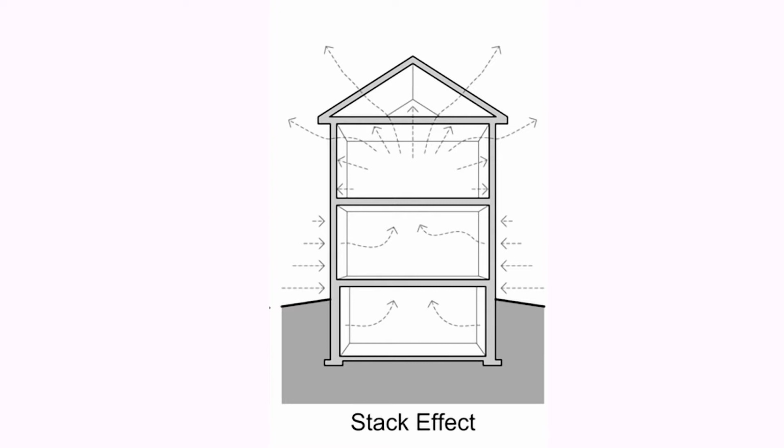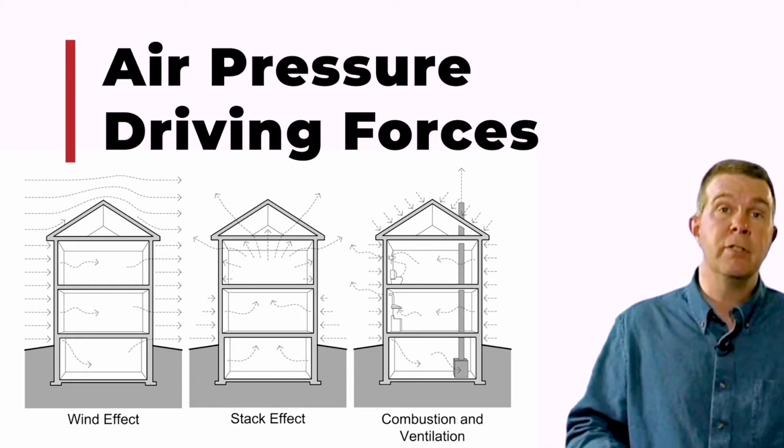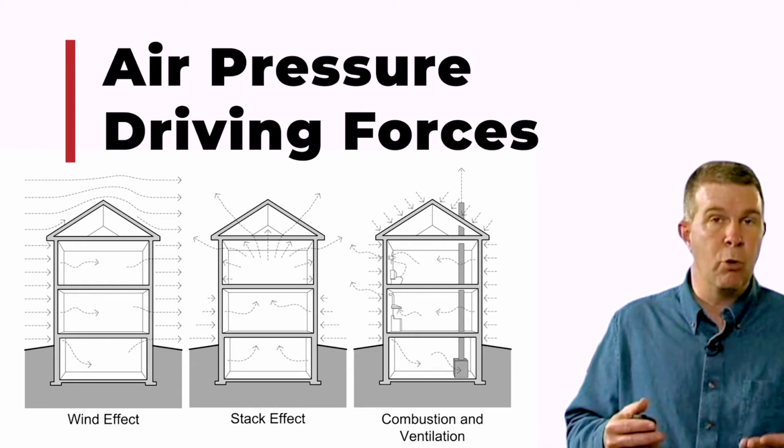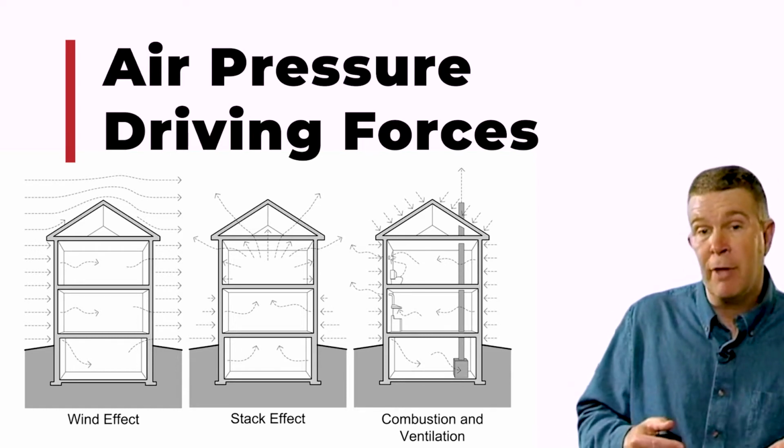You have pressure at the top and a vacuum at the bottom, and that's going to draw air in at the bottom and it's going to force air out at the top. We're making this air move where we may not want it to move because of this stack effect. And the worst thing the stack effect will do is it'll start bringing moisture and humidity and air out of the ground if we don't have that properly sealed.